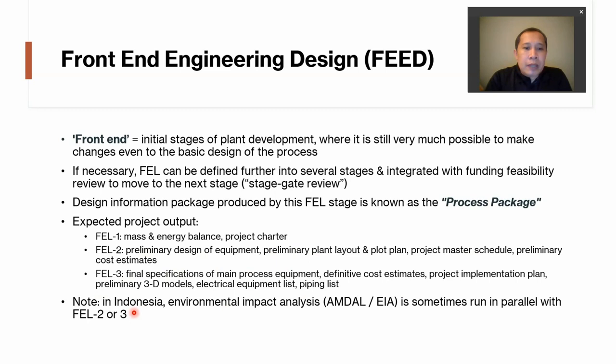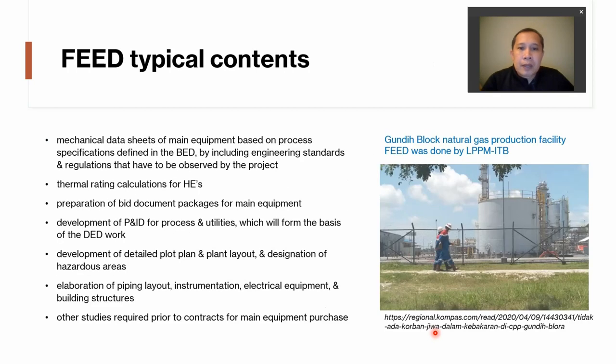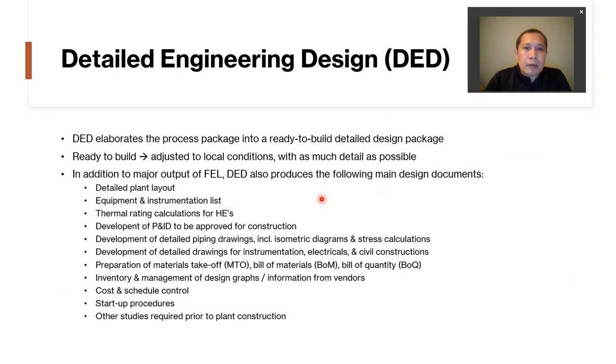And as a side note, in Indonesia, AMDAL, or Environmental Impact Analysis, is sometimes run in parallel with FEL2 or 3. Okay, so this is the typical content of a FEED: mechanical data sheets of main equipment, thermal rating calculation for heat exchangers, preparation of bid document packages, development of PNID, and so on. Okay, I urge you to read more about these outputs of FEED project.